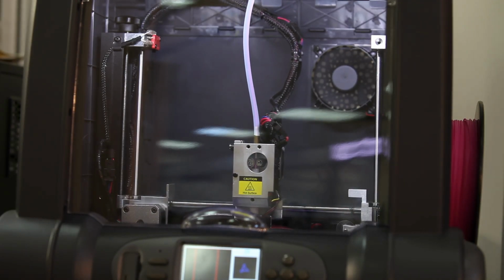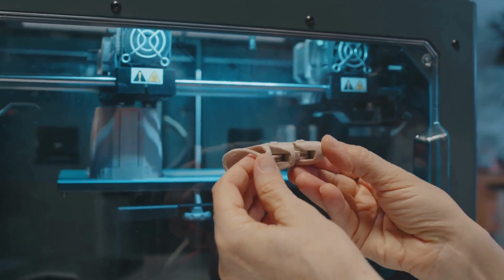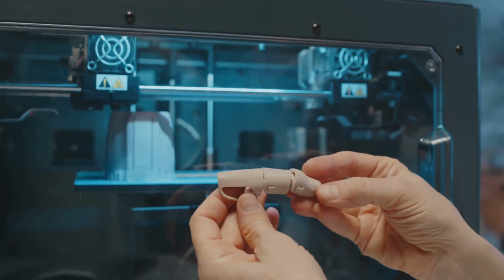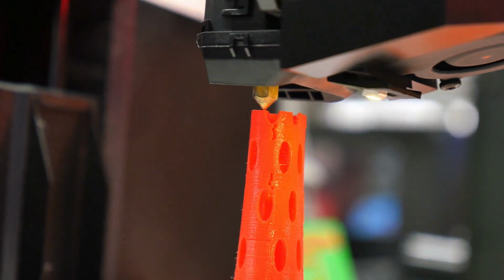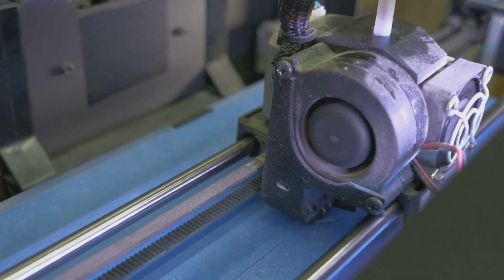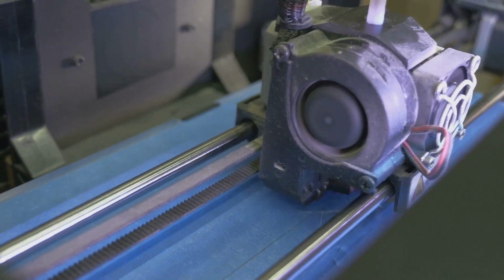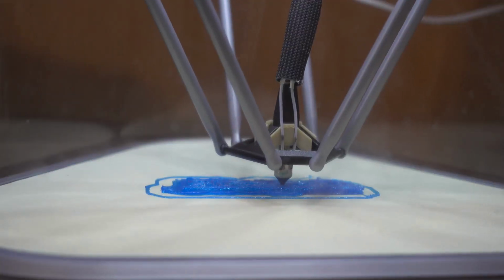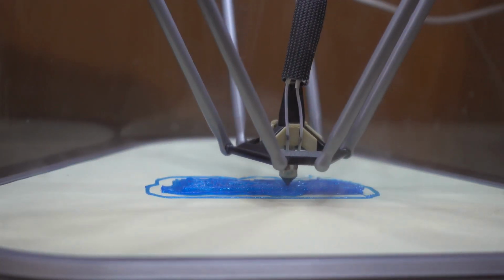While G-code dictates the movements of your 3D printer, M-code takes care of the behind-the-scenes tasks that are essential for successful printing. These commands control various aspects of your printer's functionality. One of the most critical functions of M-code is temperature control. M-code commands tell your printer to heat up the extruder to the precise temperature required to melt your filament. It also controls the heated bed, ensuring that the printed layers adhere properly and prevent warping.